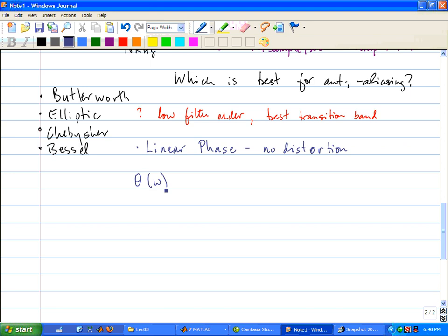When I reconstructed the signal, passing Xn through the filter and getting Yn, I saw that the 1 kHz signal has been reconstructed but delayed for some amount. So if frequency components are delayed by different amounts, then the reconstruction has been distorted.